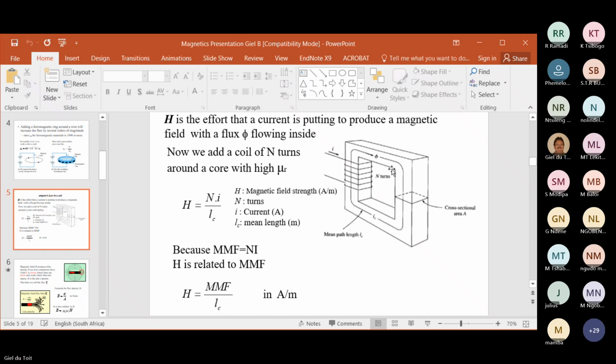That's how you get the size of the core here. So to get the average flux will flow between 10 and 8. So the average flux, I'll take that length there, in which case it's 1 centimeter on top and 1 centimeter on the bottom. So the middle of that 1 centimeter is 0.5 centimeter. So I again divide it by 2. And this 1 centimeter here, 0.5 centimeter bottom, 0.5.